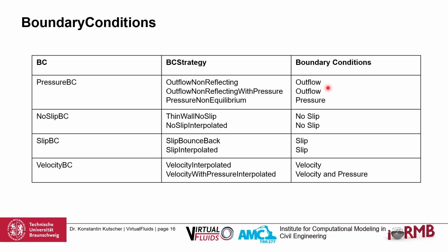If you want to set up your simulation, first of all you look at the description. Okay, what do I need? I need outflow, for example, no slip for walls, and velocity. And you look at which BC strategy matches your boundary conditions.